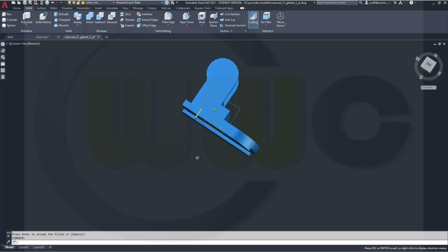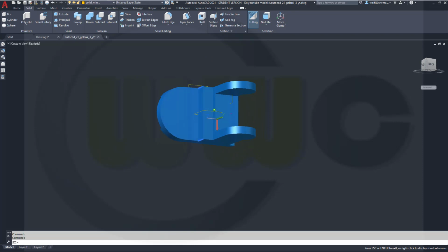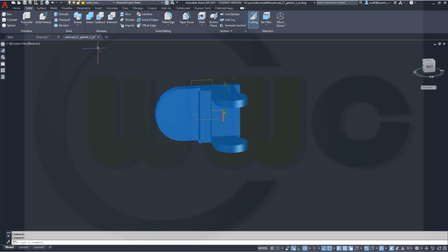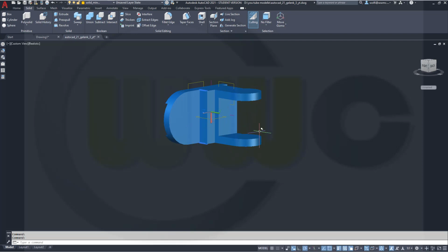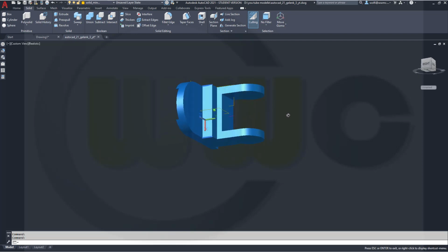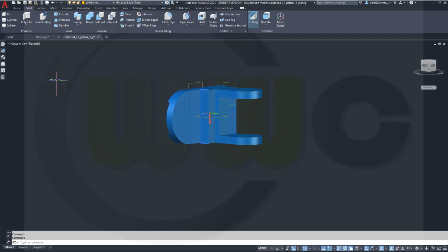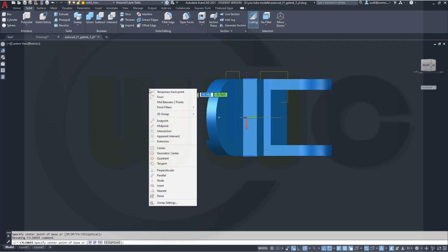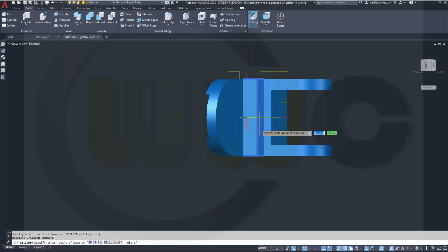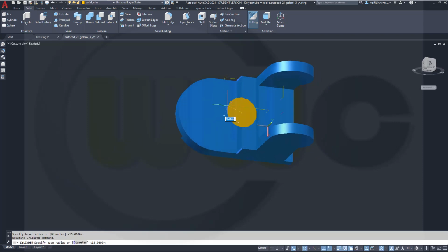Now for the holes. Let's take a look. And yeah, I could do this one because my axis system looks in that direction. So go for a cylinder. And the center point would be, of course, the midpoint of that edge. So go for midpoint and try to select here. Yes. Let's see where the cylinder will go. That's wrong. So it's perpendicular to that one.